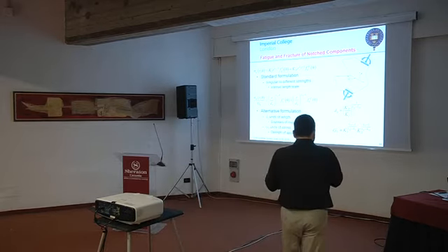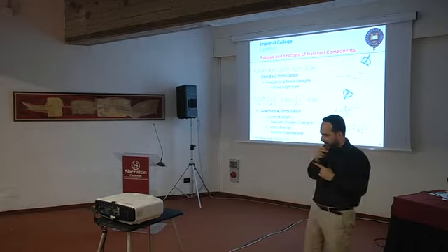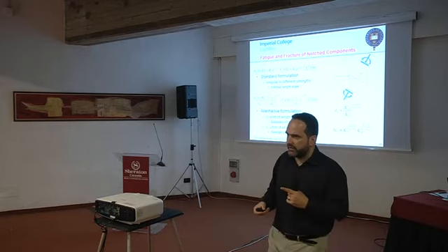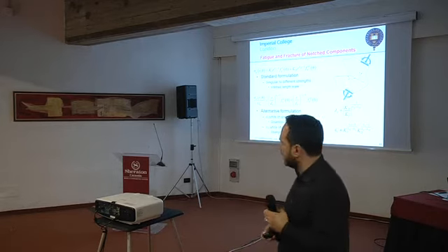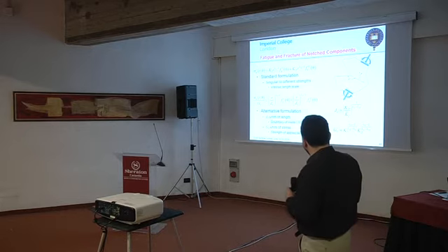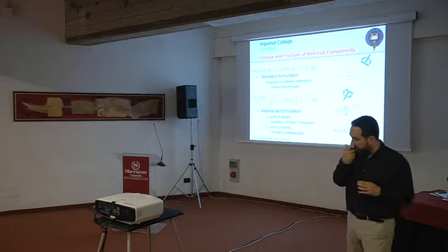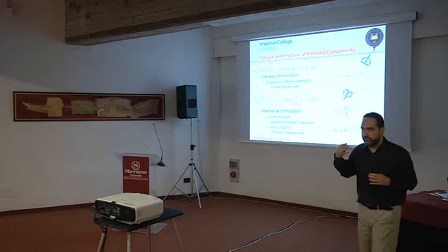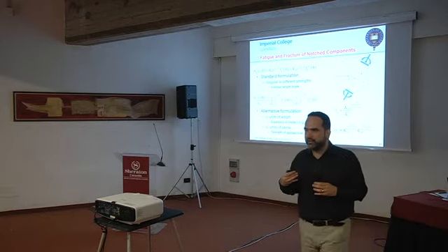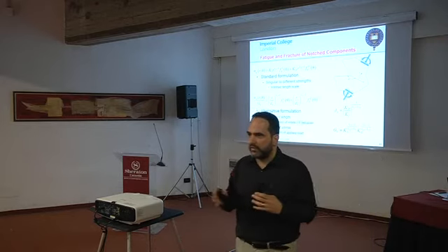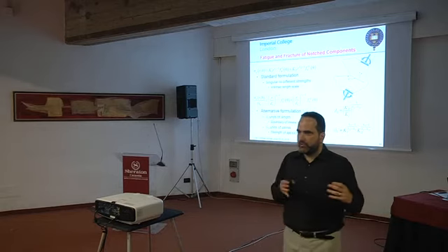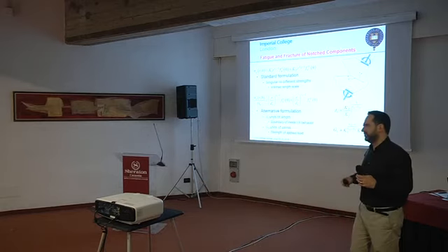And I think that's what we try to do. We try to understand much deeper how we get mode dominance. And this redefinition of Williams' solution allows you to do so, because it brings out the length scale, D naught, which will tell you almost automatically if you are in mode 1 or mode 2.